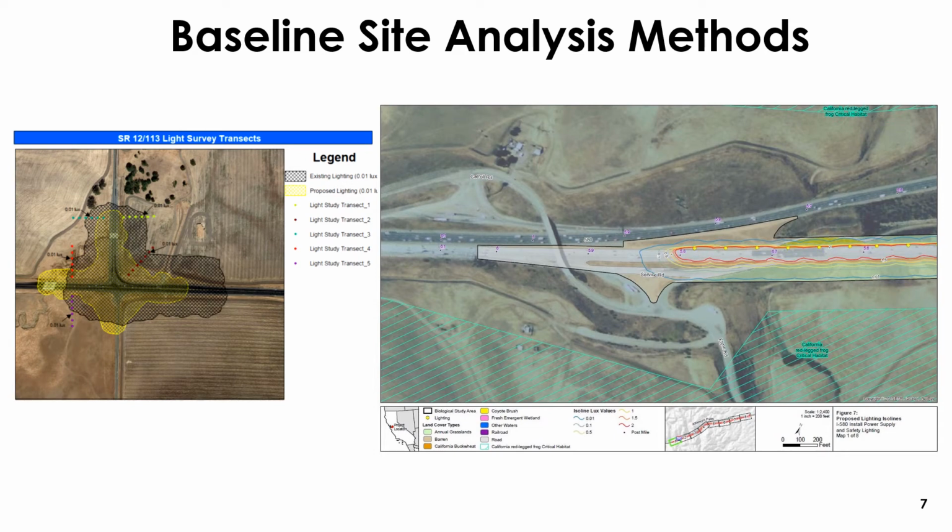The analysis for artificial light output at a given project should be divided into three specific parts. Part 1 is to develop an environmental baseline of the existing light output conditions. Part 2 is to develop a future proposed light output condition. Part 3 is to develop a system that tracks and vets the estimations from Part 2 using on-foot personnel and the line transect methodology as previously described.